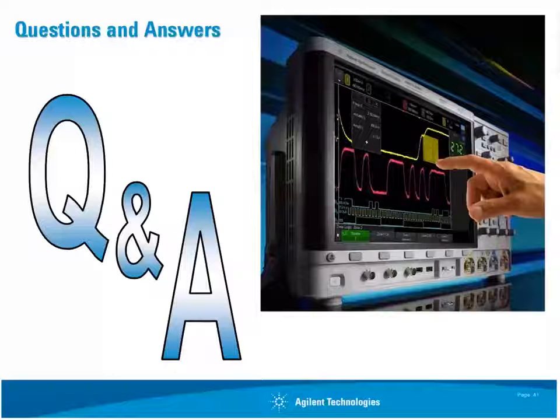The biggest one is where you set your time-based range. If you set your time-based range, let's say, at 1 millisecond per division, that means it's going to capture 10 milliseconds across screen. You have an acquisition time of 10 milliseconds. And even if the scope had 0 dead time, the absolute maximum update rate the scope's going to have at that time-based setting is 100 waveforms per second.